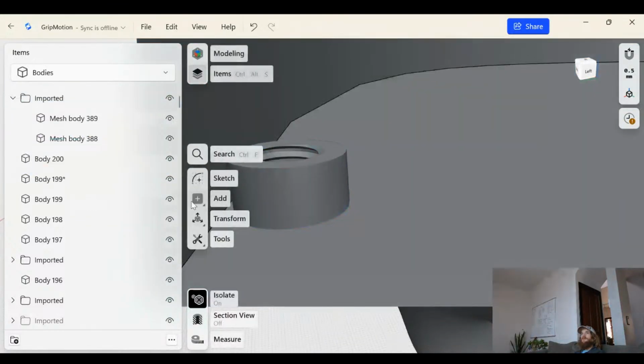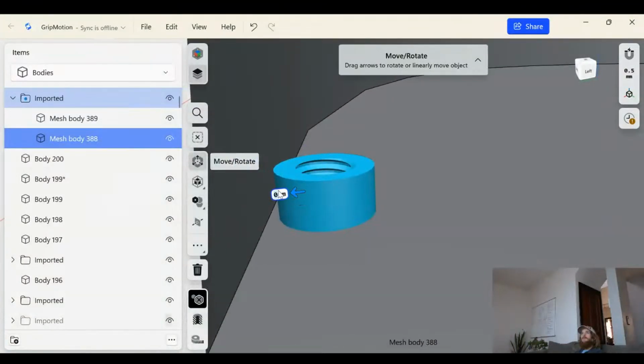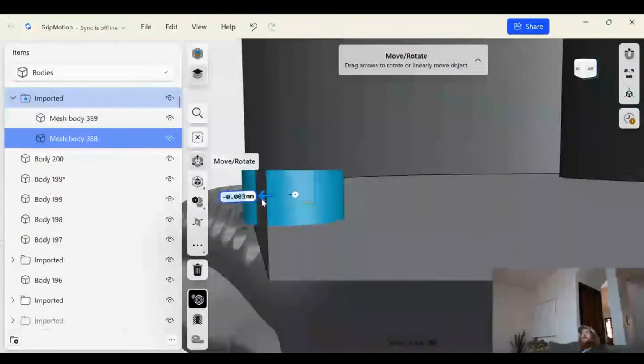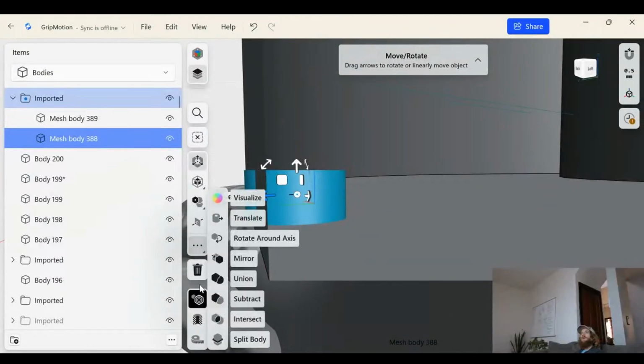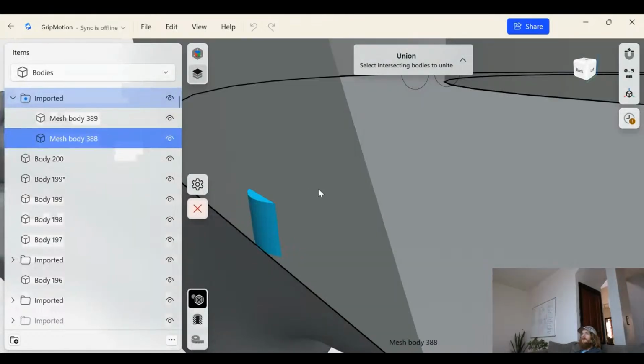Union operation failed. Sometimes it will have trouble unioning if the walls are flat and parallel to each other, and they somewhat intersect, kind of like your fingers in a weaving pattern.